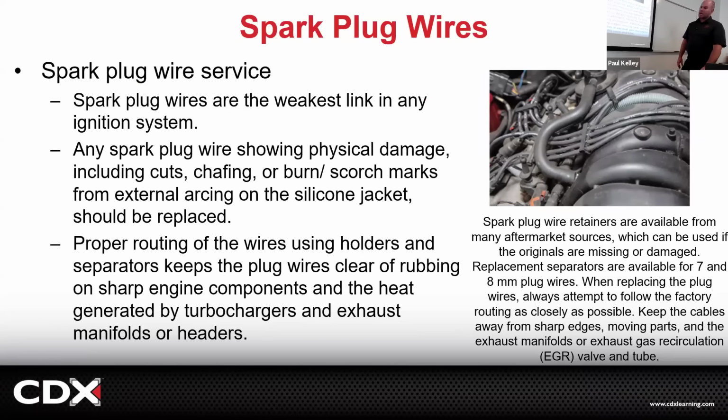Now, same with wires, same recommendation, make the marks. But there's a couple things that I must add. If these spark plug wires have damage, maybe it rubbed on the exhaust, or maybe a mouse chewed on it or something, these secondary ignition wires can't have any kind of damage.